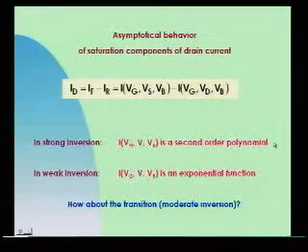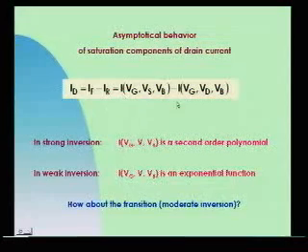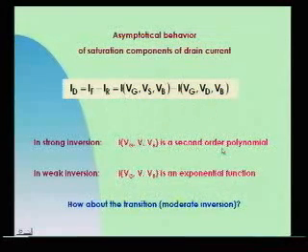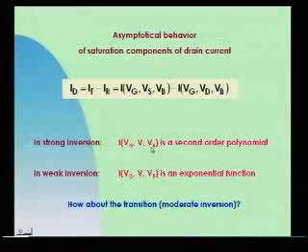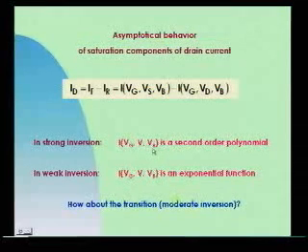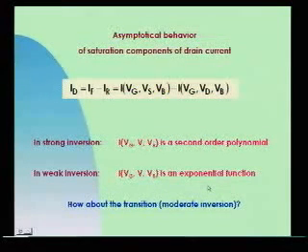That in strong inversion, its saturation component is a second order polynomial of the voltages Vg, Vs or Vd, and Vb, and in weak inversion, an exponential function.